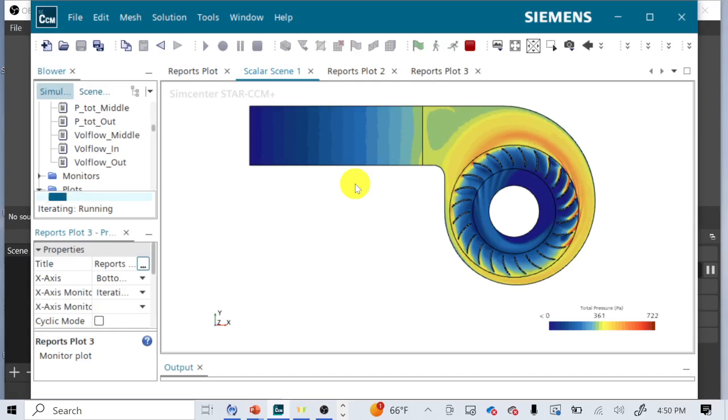So what we're really looking for is, if this is 0, we're looking for the total pressure drop, or the pressure drop here, across this section. Because the pressure came in at 0, it rose by some amount, and then it's going to fall by some amount, but it also leaves with some amount of energy. Right, we can't discount how much energy it leaves with, so we have to just look at how much this resistance generates.